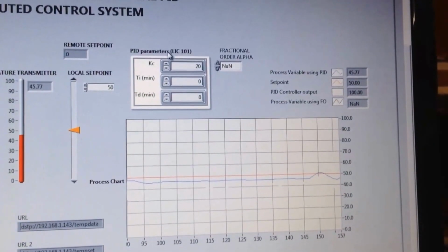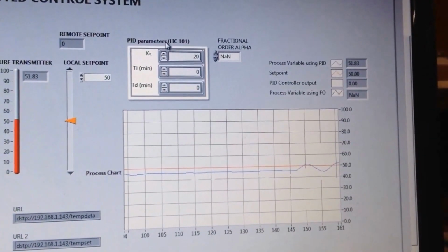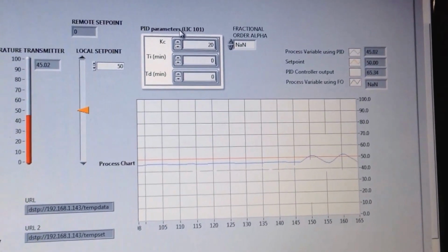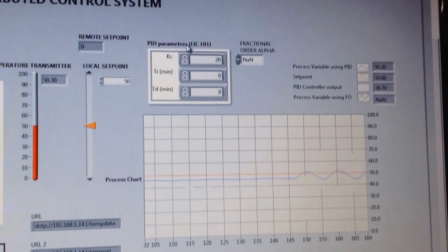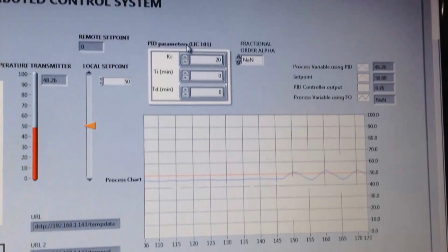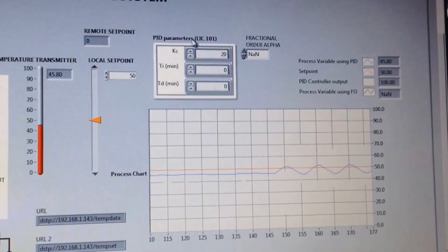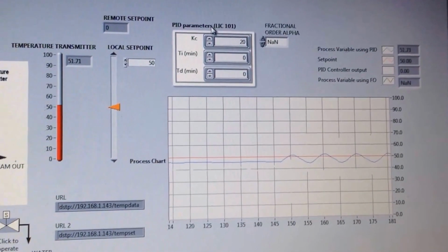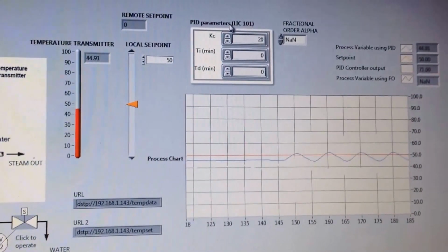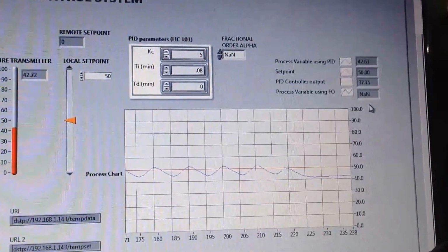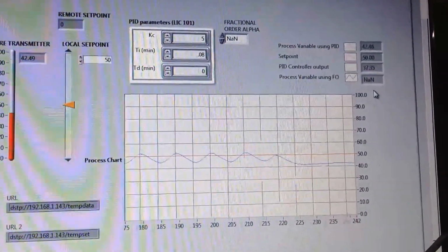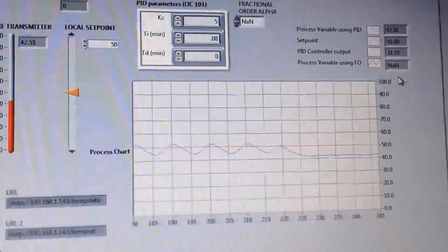The proportional gain is changed to 20%, and look what happened to the control variable. It is oscillating. This is an indication that the system becomes an on-off control. It is now cycling. We now added integral control to the system, and notice that the cycling is gone.